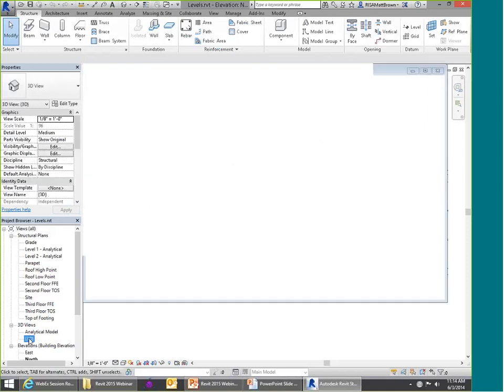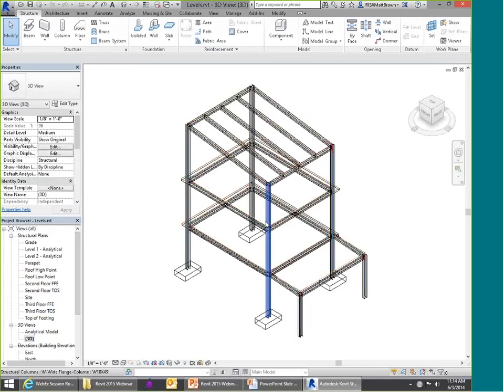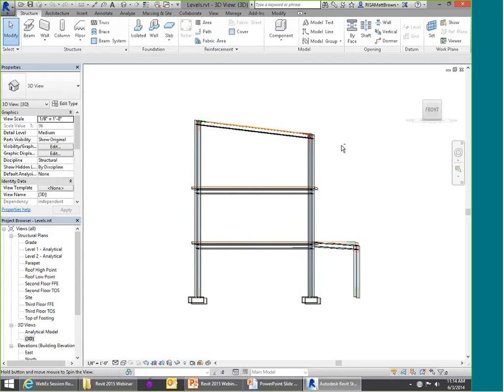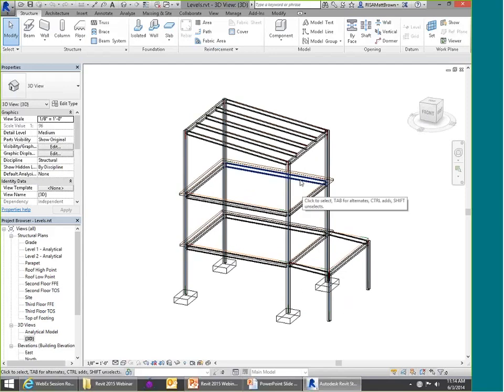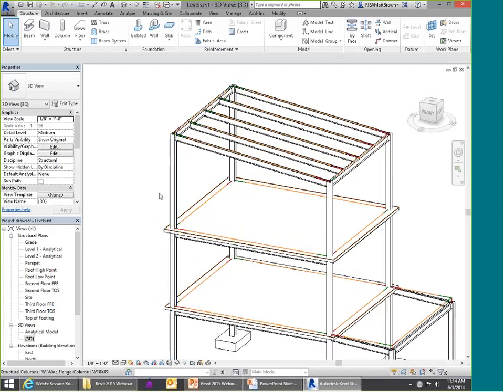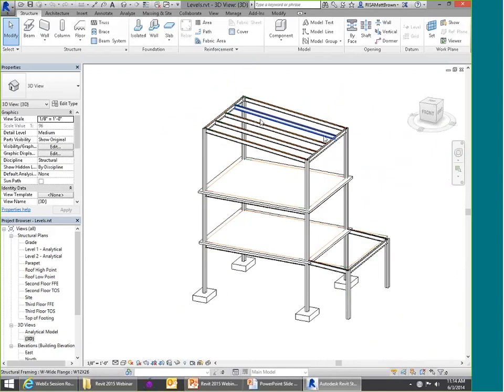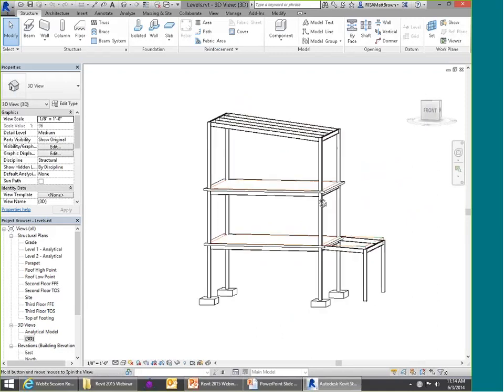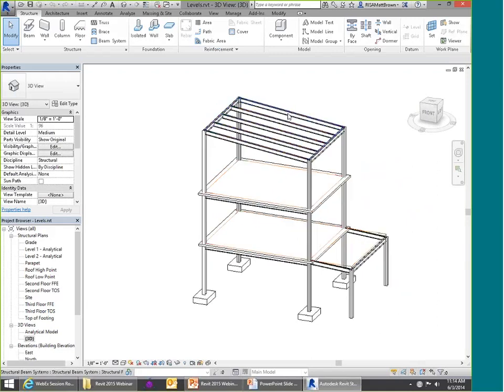And what you're going to see in this model is a relatively basic multi-story structure, but this is the sort of structure that's caused a lot of issues in the past, certainly with going into RISA Floor. Now, RISA 3D can handle just about any geometry, but because RISA Floor is a building-specific design program, it needs to have geometry fall within certain constraints. And one of those constraints is that you must have clearly defined floor levels for everything. Well, in this case, this structure, at face value anyway, looks like it does have clearly defined floor levels.